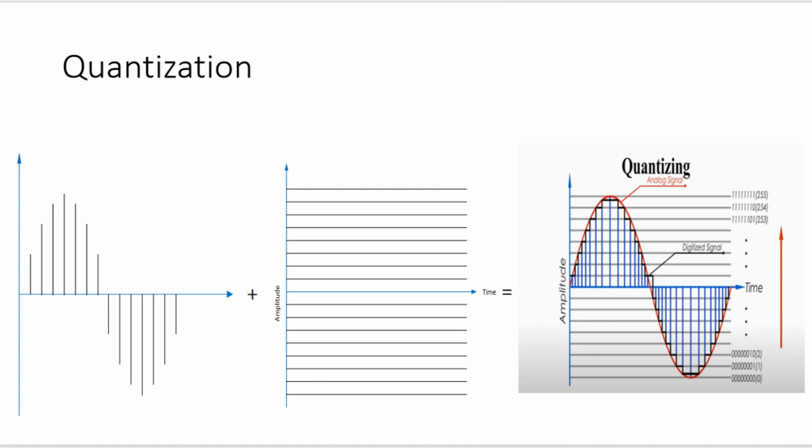the text that follows. Converting PAM samples to a digital signal involves assigning the amplitude of each PAM sample one of a whole range of possible amplitude values, which are divided into quantizing intervals. There are 256 possible quantizing intervals.